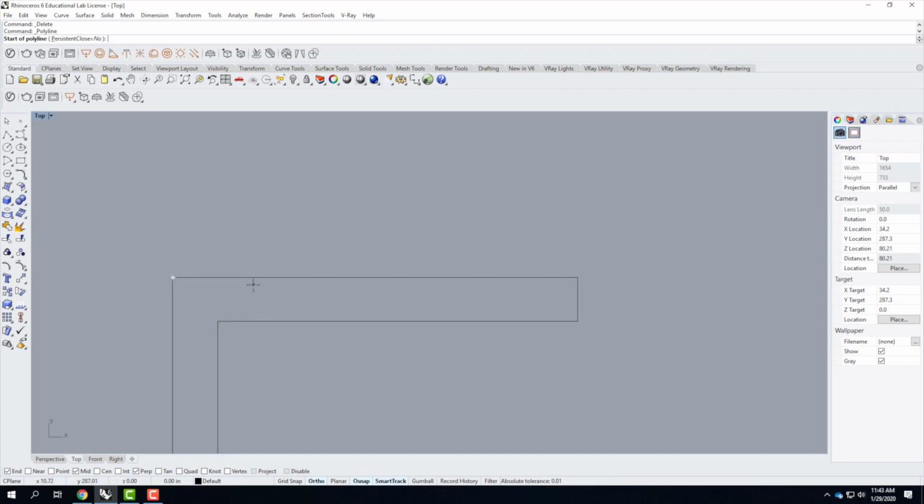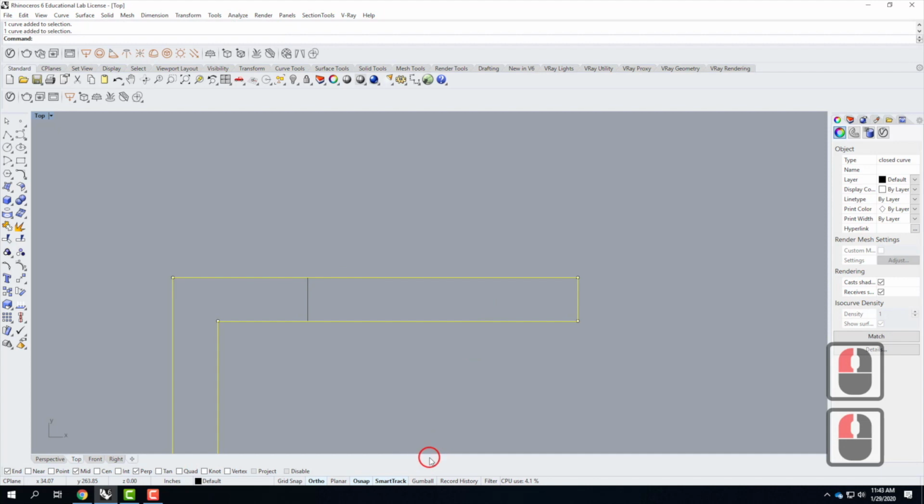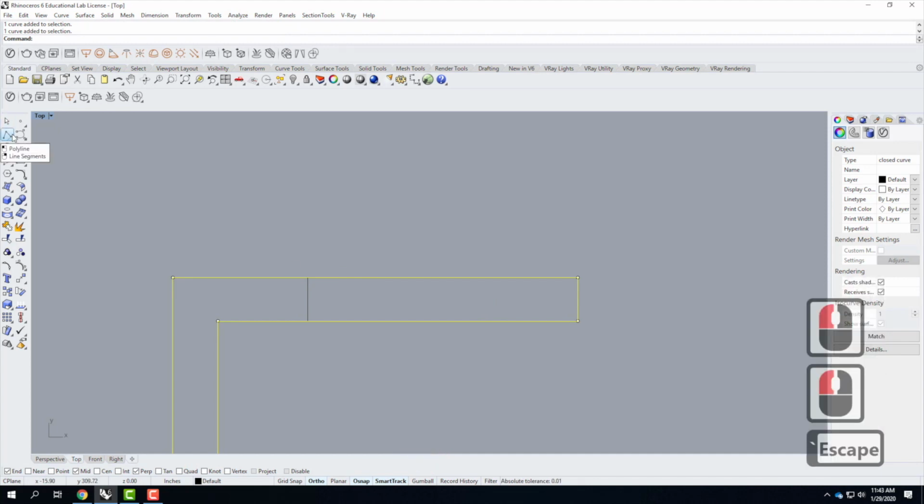I'm going to move my mouse to the right, and I now get a blue point with a white line next to it. I can now type a distance, and it's going to be a distance away from that now blue point. So I can type in 1 foot 6 inches, and it's going to start my line at 1'6" from that reference point. And so I can draw that over. And it's going to give me just the line. No other extra segments, nothing. Just the line itself.